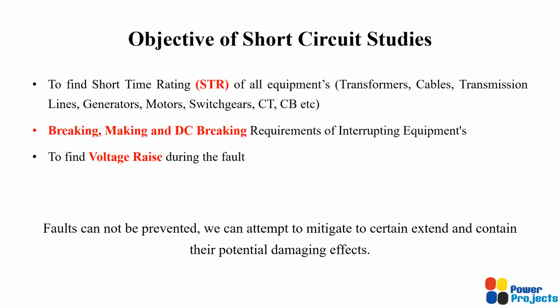Then it is important for the interrupting equipment like circuit breakers or contactors to break this short circuit current without any issues. So when you are selecting this interrupting equipment, you need to validate the breaking current, making current, and DC breaking current, which we are going to discuss in more detail in the upcoming slides.